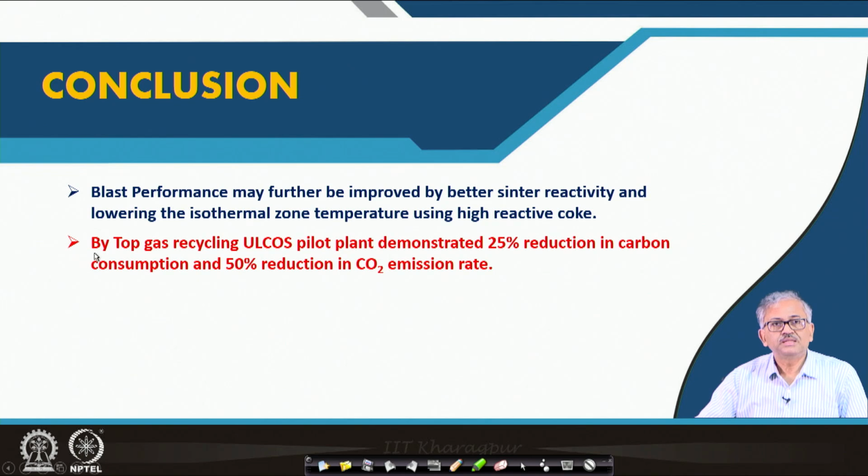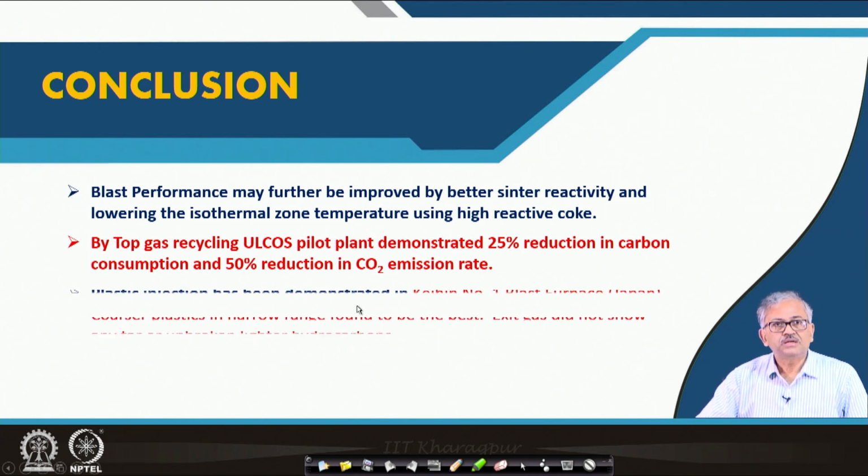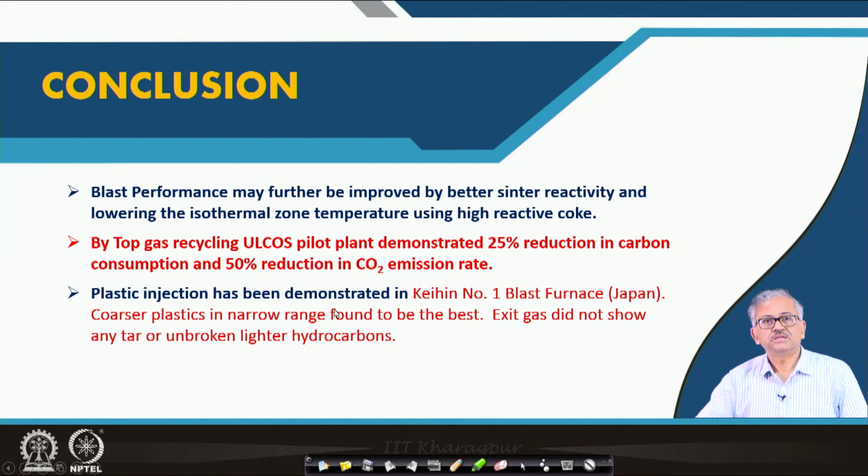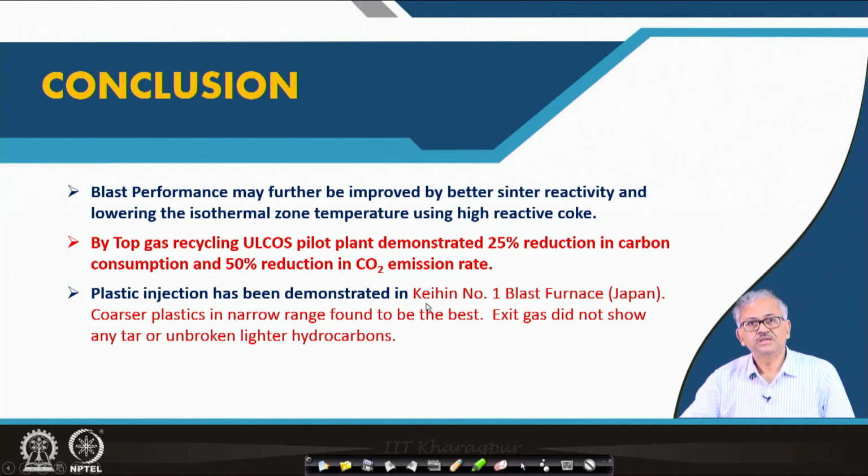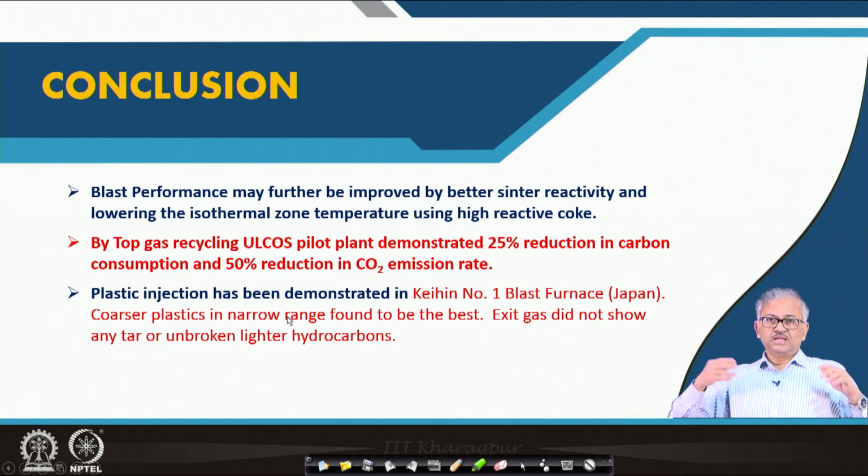Another thing is top gas recycling. By top gas recycling, we can reduce the CO2 emission from the blast furnace by 50% and overall carbon consumption by 25%. It has also been tested in a laboratory scale blast furnace in MEFOS. And then plastic injection has been demonstrated already in the Keihin blast furnace number 1 in Japan, and there are some interesting findings from their